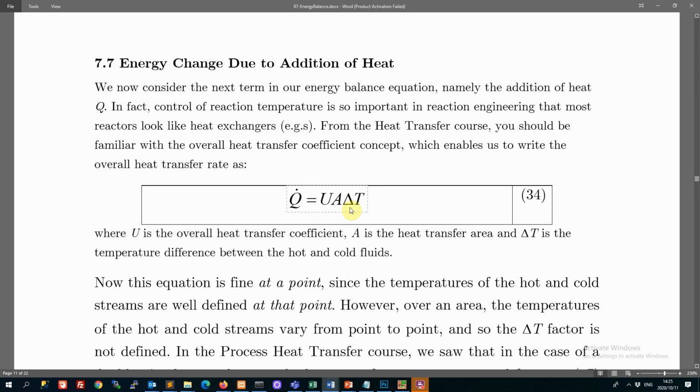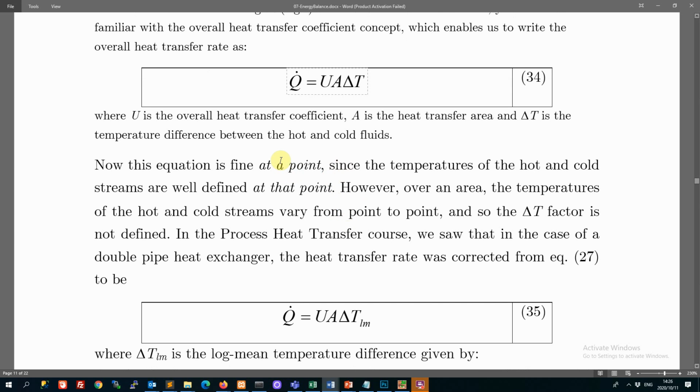And then there exists some temperature difference, right? That's why energy is being transferred in this way. And again, many temperatures apply in the reactor. You've got an inlet temperature, you have an exit temperature, you have a reactor temperature, you have a temperature in the heating coil or the cooling medium. So you have to be very careful in picking the right quantities here. If we are talking about heat transfer due to temperature difference, you have to figure out which things are different, and then that will tell you which temperatures to use here. We'll come back to this when we apply it.